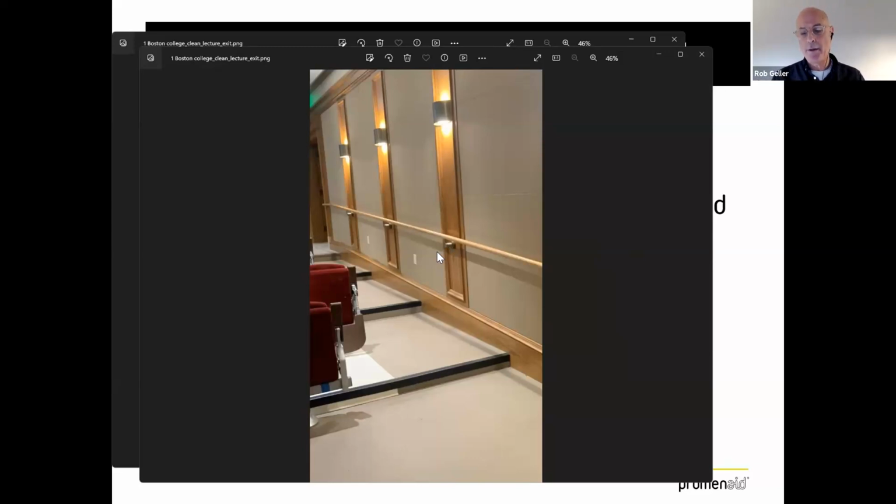And we tested it at 48 inches, at 32 inches, and we even tested it just to be safe with only 2 of the 3 screws hitting the stud. You can see that there's 3, and even if just 2 screws hit the stud, they'll support 500 pounds. That's additive. So every bracket you add is another 500 pounds.